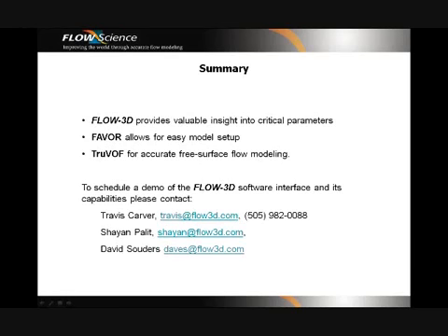Another question, what is the exact equation used for the air entrainment model? Well, I believe we derived this equation ourselves, and we do have a tech note available on our website. What we do is we look at surface disturbing effects like turbulence at the free surface, and we compare that to surface stabilizing effects, including gravity and surface tension. So we look at that balance, and depending on the ratio of the two quantities, we decide how much air is entrained. And then on top of that, we've added enhancements for jet impingement when that's important.